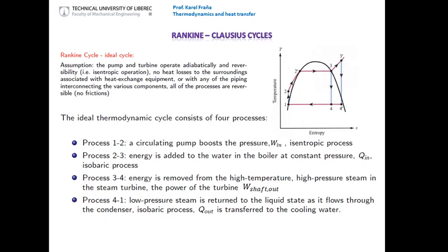Between the point 2 and 3 prime, you practically supply the energy of the heat, which is used to produce the superheated steam. The point 3 prime to 4 prime, or if you start from the saturated vapor, then it is a line between 3 and 4. You can see that it's the blue line. This indicates nothing else than expansion in the turbine. And I said you have to stop after you reach the condensation line. So the line between the 4 and 1, or 4 prime and 1, is nothing else than condensation.